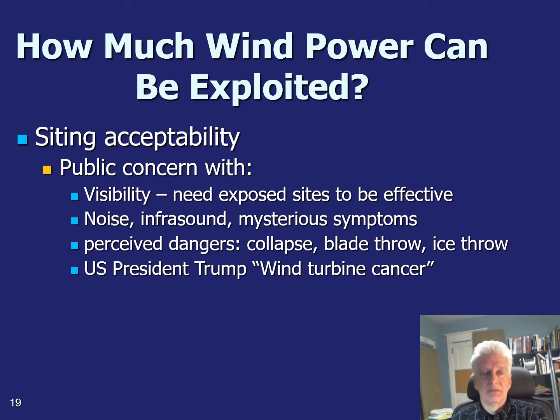Maybe the turbine might just fall over if you've done a bad job. There was one where people actually did a poor job pouring the concrete for the base. The turbine fell over, and one activist group very opposed to wind published maybe 37 photos of that one fallen over wind turbine, trying to make it look as though all of them are going to hit you on the head. And more concretely and practically, in icy conditions, ice can form on the blades, and that ice can throw off. So if you're a farmer and you have wind turbines in your rangeland, you would have to plan around that. If there's an ice storm going on, maybe that's not the day to be out in your tractor.